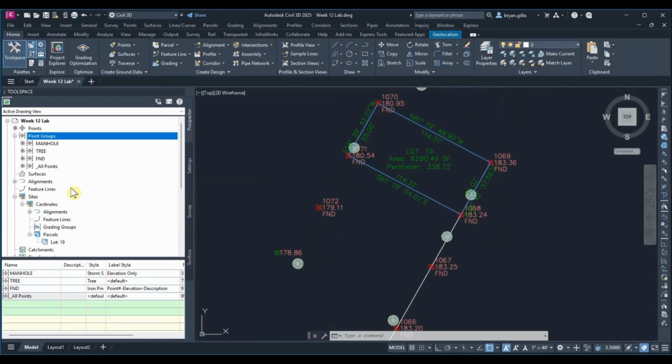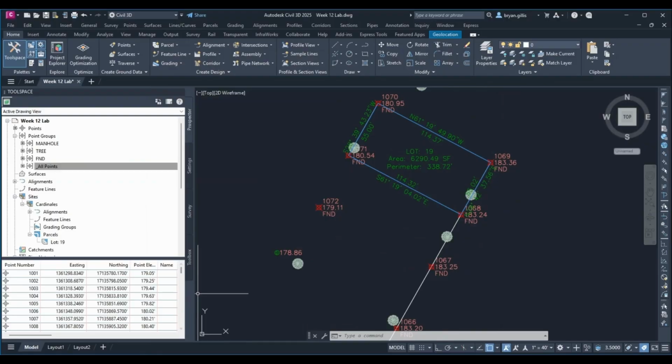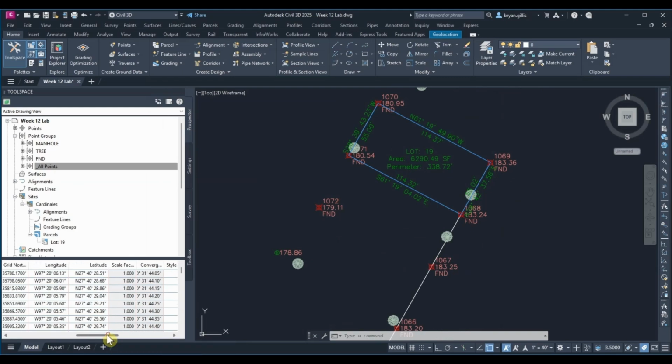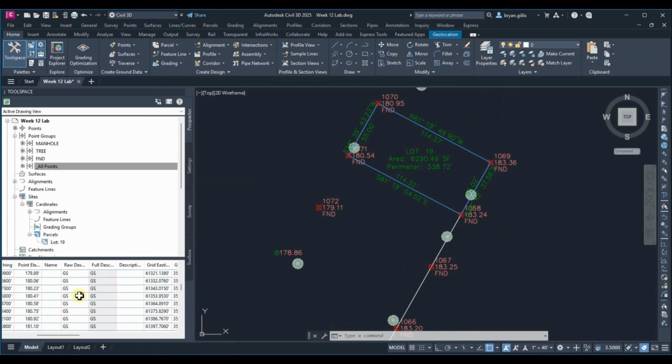I went ahead and just referred to everything as a storm drain manhole. I didn't specify if any of them were storm drains or sanitary sewers. It wasn't included in this data set, but if you were actually doing this work, that's the kind of information that you would be including as well. You'd also want to have 811 come out before you go and do your survey, and they would be able to mark any underground utilities that have already been laid.